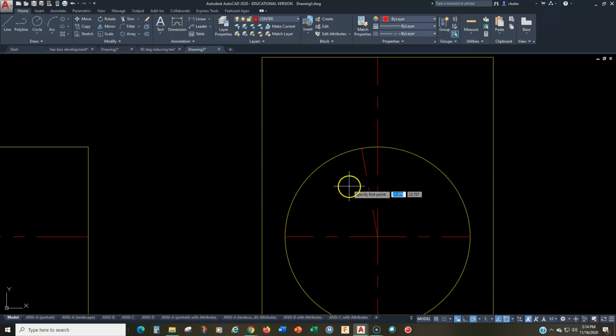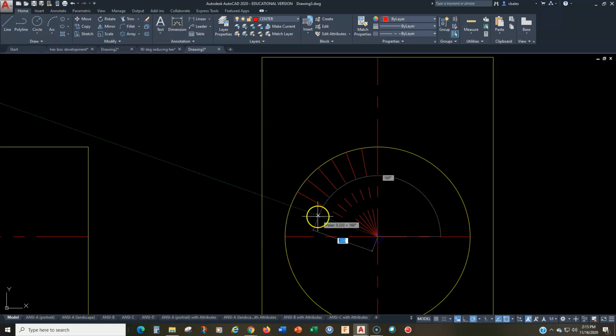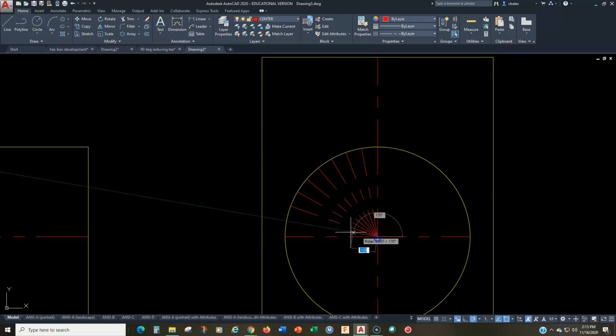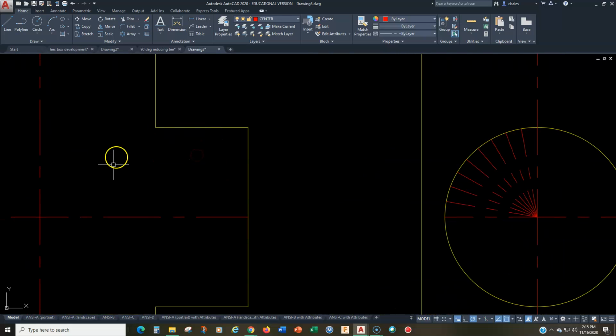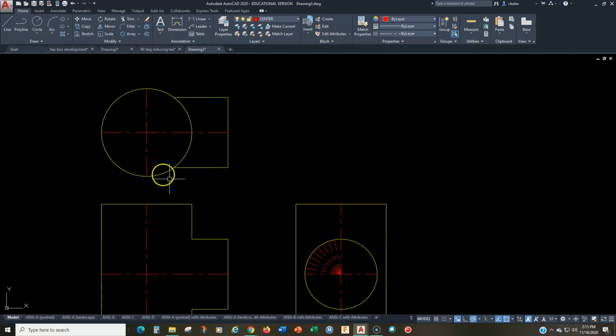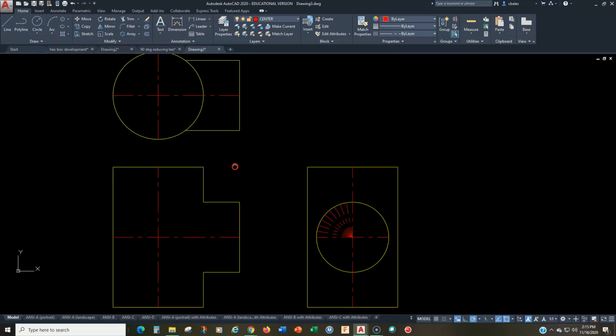Right there. So in this space right here, this is 90 degrees. I should have 9 lines, right? I should have 9 angles in there. Obviously, the more angles or the more lines, the more accurate this would be. But trust me, every 10 degrees is plenty accurate enough, as you'll see. Okay, so now I've drawn those over there. Now, I purposely put them in this quadrant right here because this quadrant in the right side view corresponds to this area in the front view, and it corresponds to this area in my top view. Okay, so there's a reason why I did this.